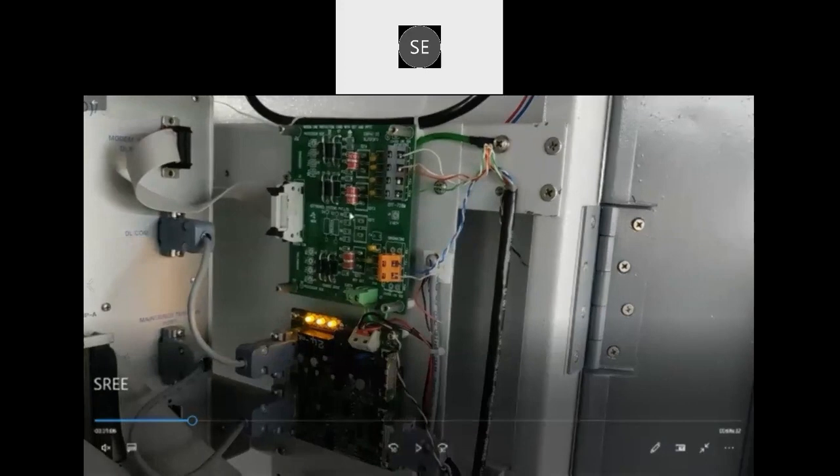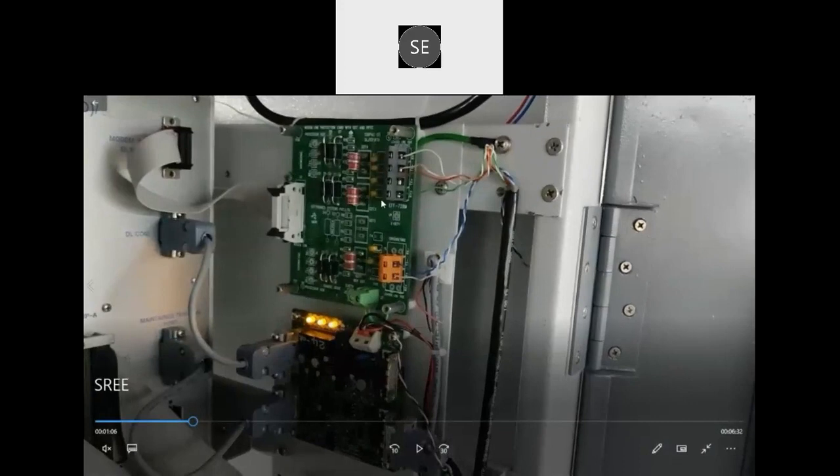So this is the backplate or rear view of the system. This is what I said, the GDT card, the second level of surge protection device, SPD, that is what we are calling. Voice lines are terminated here, and even lines are terminated here. From this card, the communication is extended to the main motherboard through this ribbon.